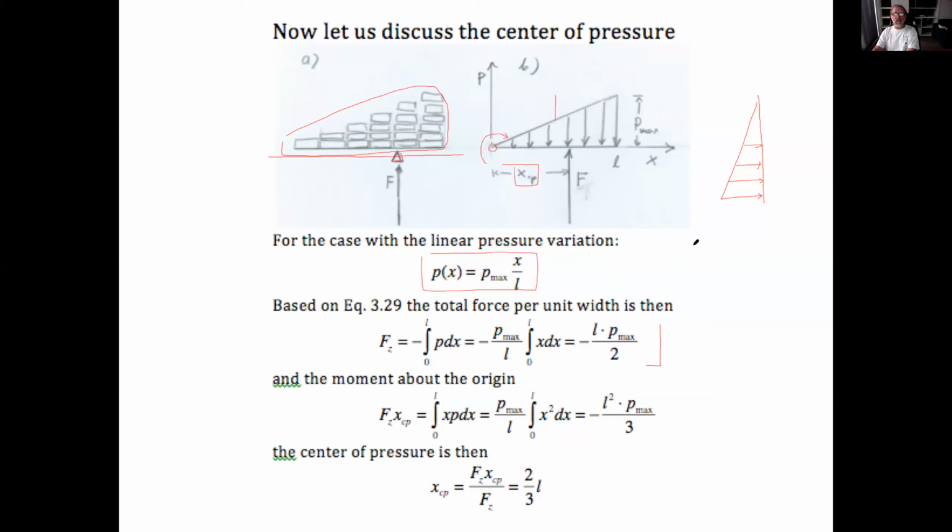And so what you do is you say the forces due to that pressure distribution will be balanced by the resultant force, and tell me what is the distance where this average force is acting. That's how the statics goes. And this is what we're doing right here. We're saying that this average force, which you already calculated, times this XCP, which you don't know, is equal to the same integral we did.